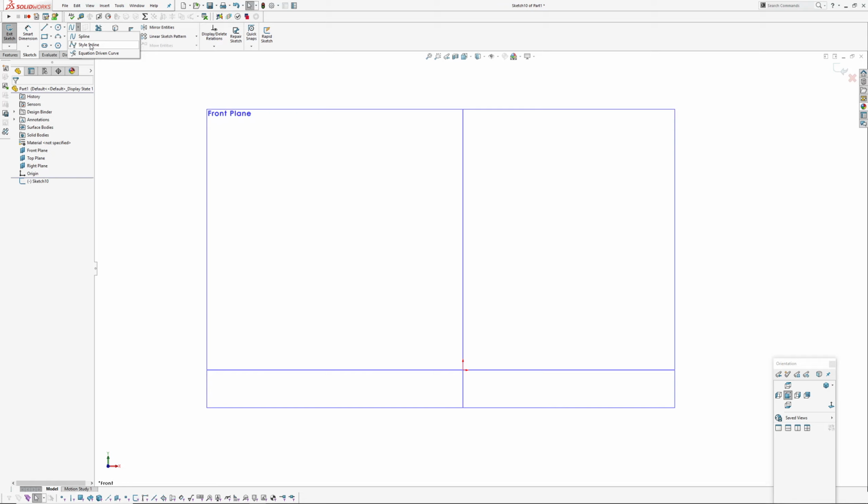the terminology and the type of splines are interchangeable between other software like Rhino, so I find this quite good to use. If you're in a sketch and you click Style Spline, the first thing that pops up is whether you want to create a Bezier curve, or a B-spline with a fixed degree of 3, 5 or 7. Without going into much detail, go online and have a look on the Rhino website. There's a great explanation about curves and multiple span and single span curves, surfaces, etc.